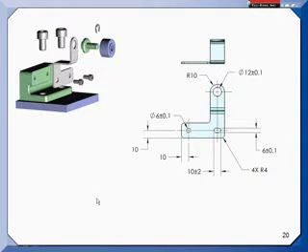Now, what I really wanted to get to is this bracket. As we look at the bracket, it mounts up against this surface. I put these two screws in there. This screw is a nice fit in that hole. And once I have it up against that surface and that first screw in, the only thing this can do is rotate. So I have the slot, a very robust way to stop the rotation. The slot isn't very critical left and right, because it's only taking away that one degree of freedom. I only need that top and bottom.